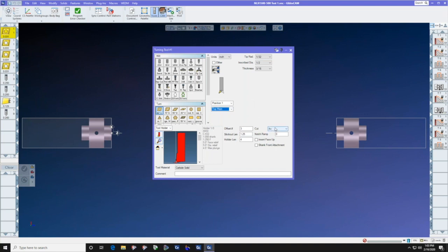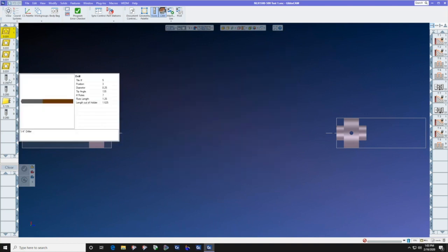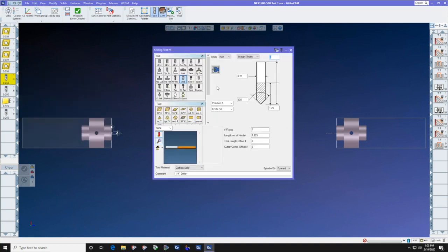And we also have a new button over here that says cut X plus or X minus, since the upper turret will cut on the plus side of X and the lower turret will cut on the minus side of X. Let's go look at the drilling tools for the front face. And yes, their orientation is pointed left. It's in turret position 3. Since this machine only has 1 turret, you can see there is no turret selection.